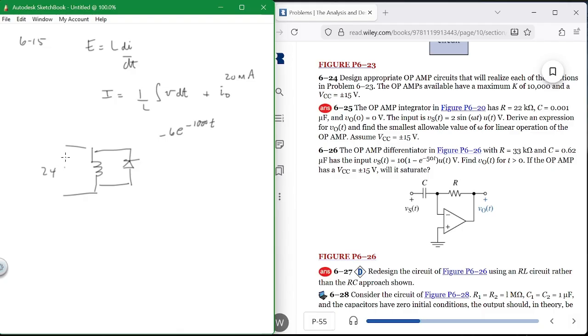So when you put 24 volts plus to minus, this flows, right? And you get a relay action. But when you turn it off, what happens? That current in that has to go someplace until it dies. And you want it to do this until it dies. If you don't, what happens? It goes somewhere. It'll go anywhere it can, and if there's a transistor in the circuit someplace downstream, it'll blow it up. Say what? It will mess with it. It'll work a couple times and then it'll go away and it'll never come back. And you'll say, now what happened there?